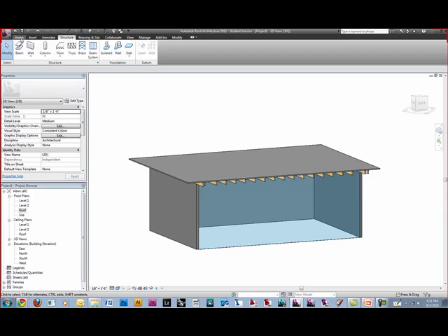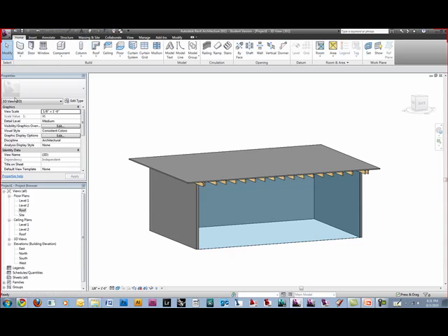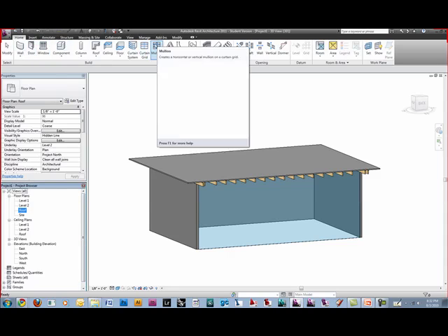Kind of this is one of those things, like I would always use a piece of sheet glass. For instance, when you're starting your model, use generic walls and sheet glass, just regular curtain wall 1, because you don't want to have to go back and delete everything just to redo something you could have prevented in the very beginning. You're going to change generic walls into something later on, so why not do a generic curtain wall? And the generic version of a curtain wall is just a piece of glass.